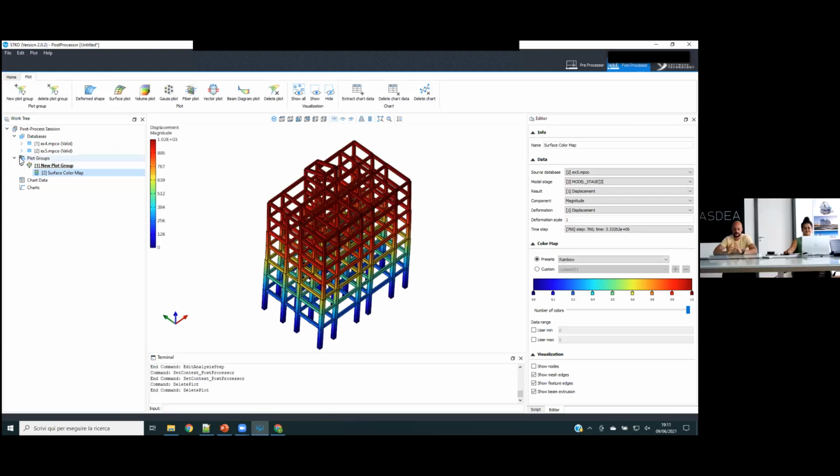OpenSees is very flexible. OpenSees does not have a moving load inside, something that changes during the iterations. But there is a way to simulate this in STKO and OpenSees. You have to do it in an explicit fashion. For example, you can change it step by step, not during the iteration, because it can be done in Tcl code.